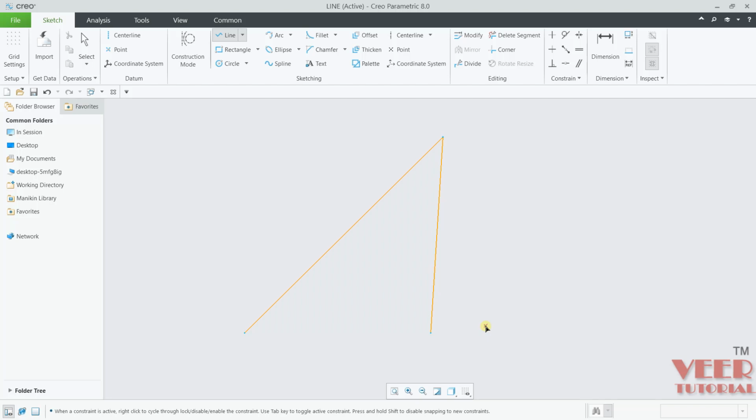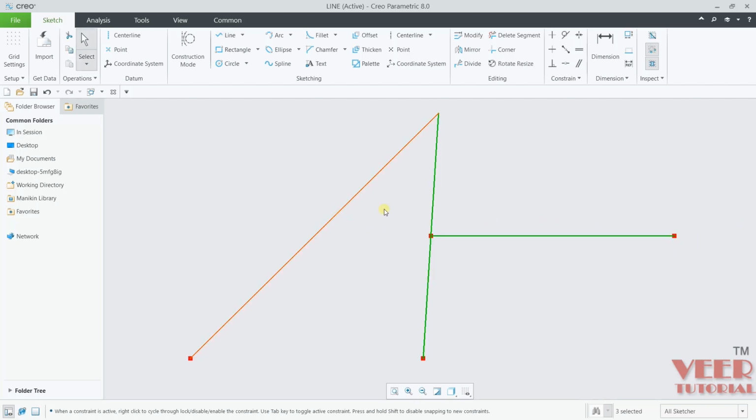This is a use of the snapping feature. Similarly, when I take the mouse onto this line without clicking and then drag the mouse, with this I can snap the endpoints using these yellow color points highlighting. I can also snap the midpoint. You can see this is the midpoint highlighting. So I can snap this, click on this and then create any line. Press escape, double escape once again.